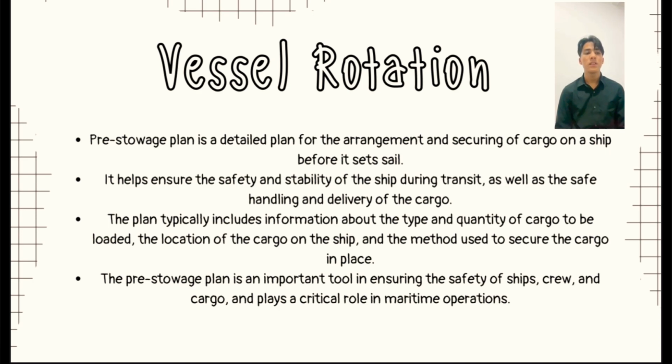The ability of various types of cargo to be stored together without endangering the cargo or the vessel is referred to as cargo compatibility. The International Maritime Dangerous Goods, or IMDG code, must be followed, and safety is a key component of the cargo storage strategy. This code offers recommendations for the safe storage, labeling, and management of dangerous products during marine transit. The IMDG code further specifies criteria for the provision of emergency equipment and procedures on board as well as for the training of crew members and the stevedores.